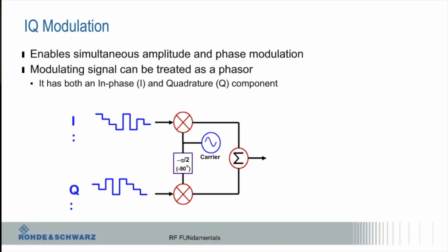There's a baseband I, which really isn't anything to do with whether it's in quadrature. It's just that the data bit stream has been split, depending on how you do the mapping. But you could say, if you had 1, 0, 1, 1, 1 goes to I, 0 goes to Q, 1 goes to I. So you're now at half the bit rate, but they don't necessarily go every other. Then you're just summing those in RF.